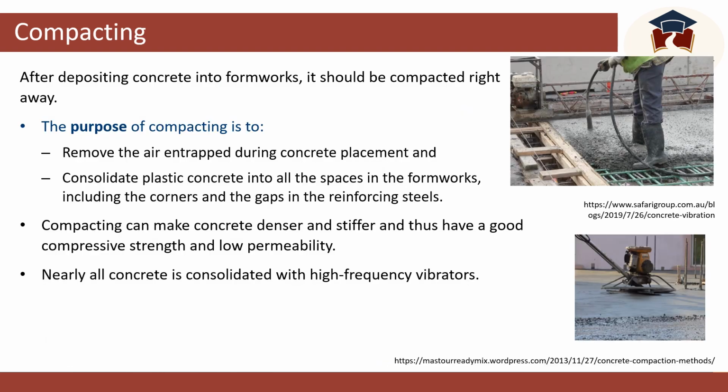After depositing concrete into formwork, it should be compacted right away. The purpose of compacting is to remove air entrapped during the concrete placement and consolidate plastic concrete into all the space in the formwork, including the corners and the gaps in the reinforcing steel. Compacting makes concrete denser and stiffer and thus gives good compressive strength and low permeability. Nearly all concrete is consolidated with high frequency vibrators. You can see some pictures here with different ways of compacting concrete.